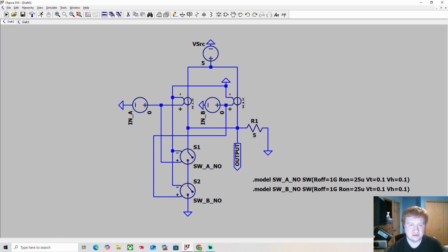It's the same voltage source, just available at 2 points. And then because 0 volts is also going to the other switch, this switch stays open. So there's no path to ground. So we've got a 5 volt signal coming to this resistor, which means that there's going to be 1 amp.